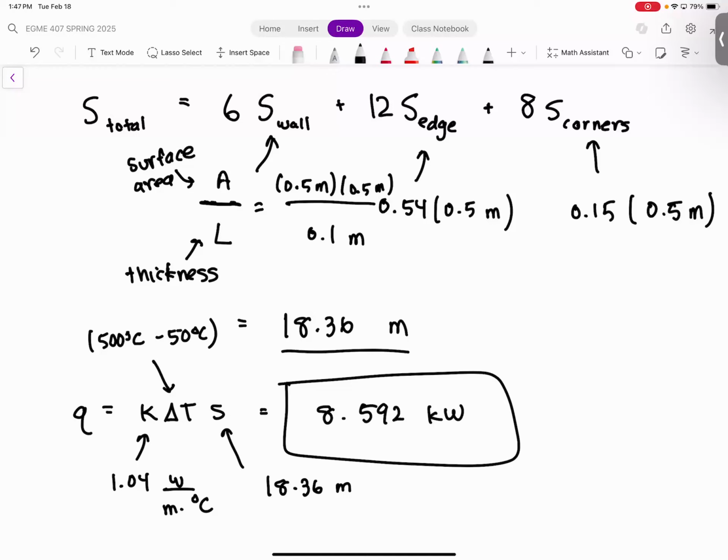All right, so that's shape factors, and the idea with shape factors is to just look up in the table, see if you have something in the table that matches up with your geometry, and then just use that as the shape factor. Okay. There is one last thing I want to go over with shape factors before we move on, which is you can actually combine it with thermal resistances. And your homework actually does that as well, for homework 3.